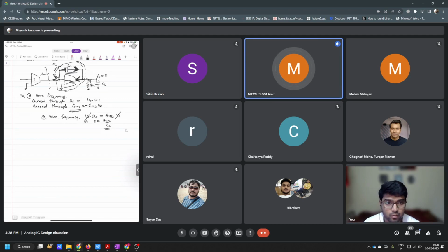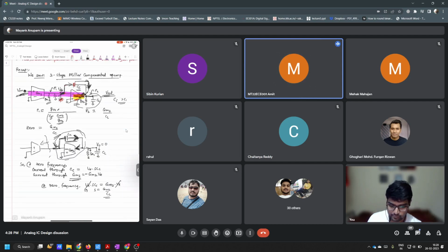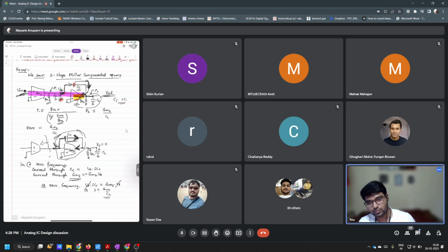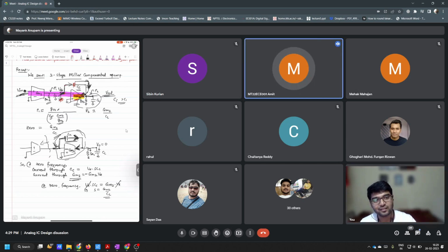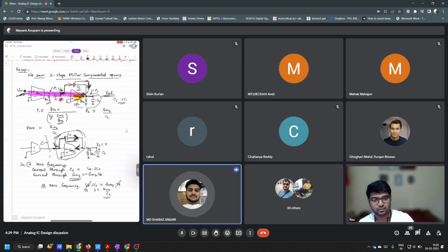Yes, sir. Sir, can I ask you a question from the previous assignment about the zero? There also we have to find the zero frequency. Yeah, tell me. I used the formula GM2 by CC. I got CC correct in the answer, but I got the zero wrong. If you have made no calculation mistake, then it makes no sense. In assignment 2, the question also has zero equal to GM2 by CC. Yeah, the zero is GM2 by CC only. I think you forgot to convert to hertz, in megahertz. GM2 by CC is in radians. You have to divide by 2 pi, then you get hertz, but they asked for megahertz.